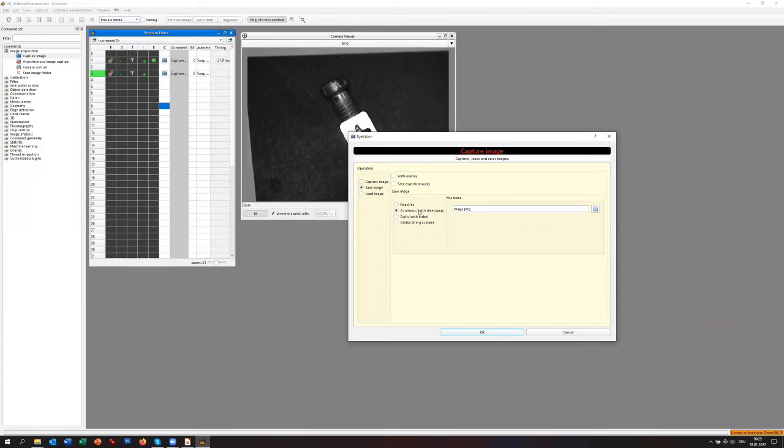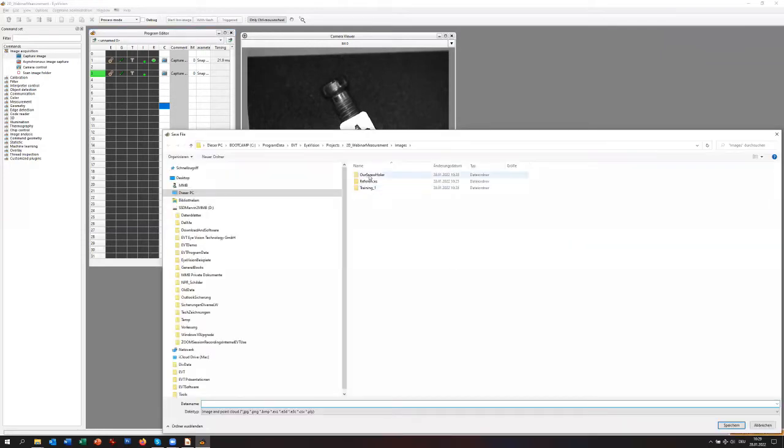We save multiple images, so let's say continuous with timestamp. Of course, if you want to measure and test this measurement with good accuracy on stored images, in this case, in contrast to yesterday, I recommend using the PNG or the BMP extension to have an uncompressed image.